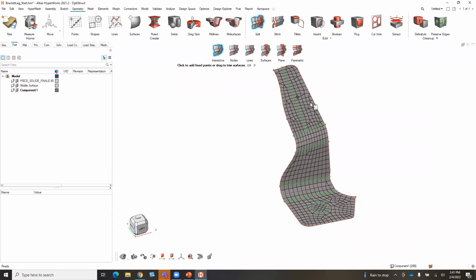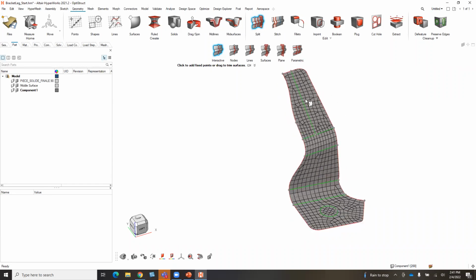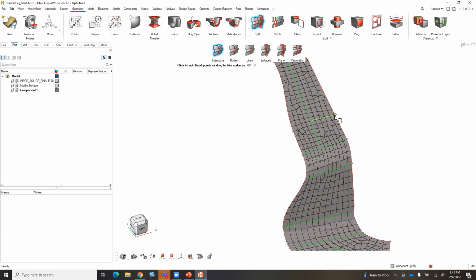And you see when I do that, it interactively, automatically creates that split for me, and then it also adjusts the mesh density automatically for me. This again is a common workflow I'll do. If I start seeing problem areas, I might split some faces so I can distribute my element density a little bit better. So that's something very useful I'll typically do.